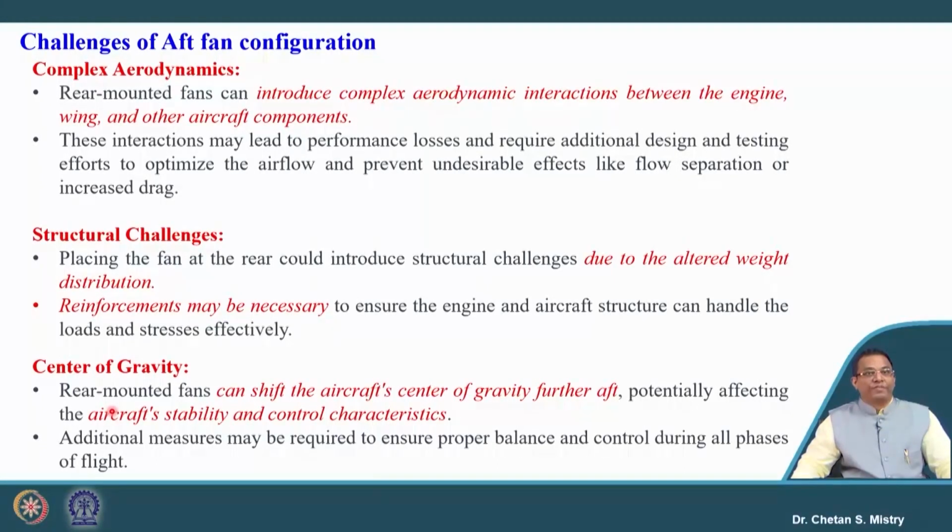So, aerodynamically, putting this kind of engine, or engine integration with the aircraft, requires careful consideration. Same way, structural challenges also will be coming, because the introduction of this engine will alter the weight distribution. We have seen these engines we are putting on the aft side, on the rear side. At the same time, reinforcement is also equally important, because when we are fitting this engine on the fuselage, we need to be very careful in terms of placement, because it will be increasing the load as well as stresses.